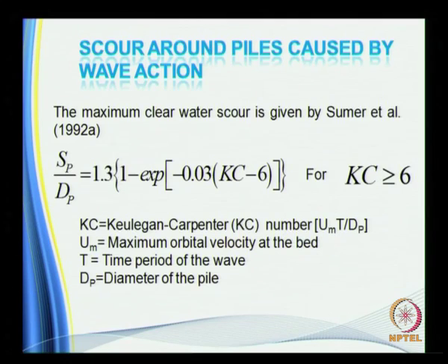Scour under piles caused by wave action. This is basically a function of the Keulegan-Carpenter number. The Keulegan-Carpenter number is U max T by D. So this equation is quite straightforward, but it is valid only for Kc number greater than 6.